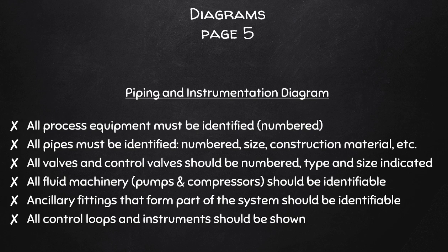What you should do is draw the process only from left to right, break up the process into its different unit operations or process sections, and use new pages for each of the process runs that you are specifying. Never ever wrap your processes along the page.